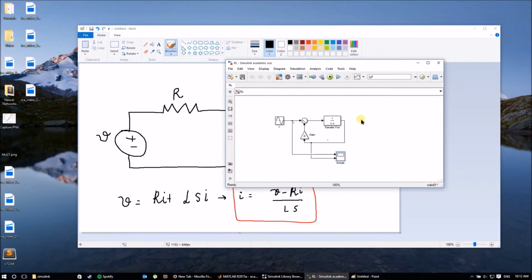So what we have to do now is, again like with the PSpice model, we have to do two things. We have on one hand to write the outputs to be saved. That's the outputs you want to save because you will use them to plot, and you will use them to plot against experimental data to find the true values. And also you need to modify the model in such a way that some parameters are treated as unknowns by parameter optimizer. So let's do that.